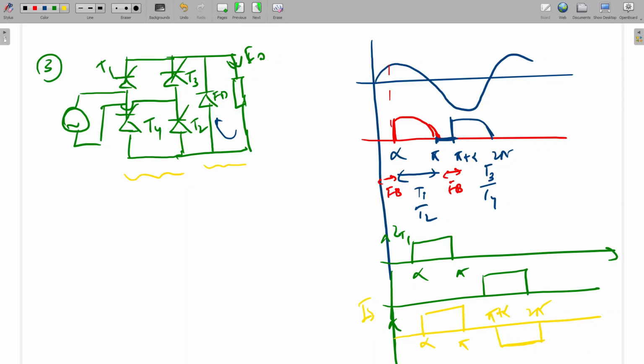Is it clear? Sir, for IS, IT1 minus IT4, sir? Yes, sir, this is IT4. So here we can say this is the entering current, this is going here, and this is going here. So IS plus IT4 should be equal to IT1, so IS should be equal to IT1 minus IT4. Is it clear? Yes, sir. So we can apply the nodal equation here, the simple nodal equation.